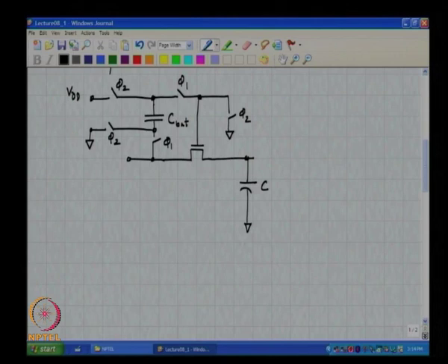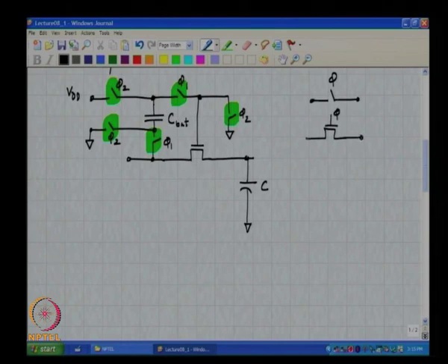All right. Now, the question is, how do we implement these switches? So, we have 5 switches in all, which also need to be implemented with transistors. And let us just quickly recall that if we want to have a switch which has to be turned on during any phase phi, there are at least 3 ways of doing it. One is to use an NMOS transistor whose gate is clocked at phi. Another one is to use a PFET whose gate is clocked with phi bar, and the third one is to use a combination of the two, also called the transmission gate.